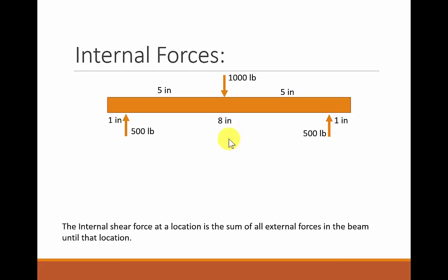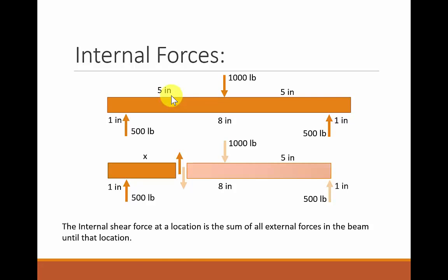So at the end of the day, what I care about is the stresses that are occurring within a part. And so to take a look at that, let's consider what would happen if we break this part into pieces. So what we're really going to do is make a free body diagram of part of the element. So let's say we break it maybe somewhere right in here. We're going to say the distance from the beginning is now considered x. So we're breaking it at x.